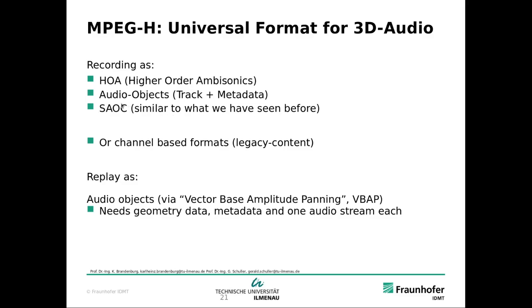So MPEG-H includes SAOC, but also higher order ambisonics or channel-based formats for legacy. Yeah, and we can also replay as audio objects via the so-called vector-based amplitude panning. This needs geometry data, metadata, and one audio stream each for playing back in a certain position.